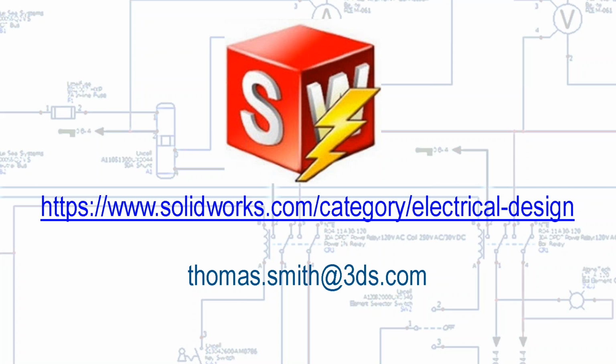Does this link to SOLIDWORKS to route harnesses? Yes. We have an add-in into SOLIDWORKS Electrical 3D, and essentially it allows SOLIDWORKS Mechanical to communicate into that SQL database so we can share project information between the two organizations. As we populate the schematics, those components can become available to the mechanical guys who can connect those up. Once they're associated, all that wire connection to-from information is brought over, so that we can route accordingly.